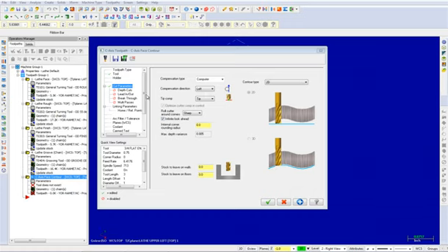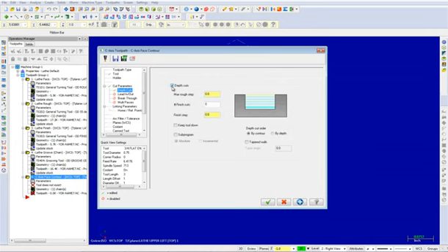From here, choose depth cuts and enable the option while inputting a max rough step of 0.25. Depth cuts are the Z-axis cuts that the tool makes in a contour toolpath. Max rough steps set the maximum amount that can be machined in one step. By contour enables the system to complete all depth cuts in the first contour before moving to the next one.